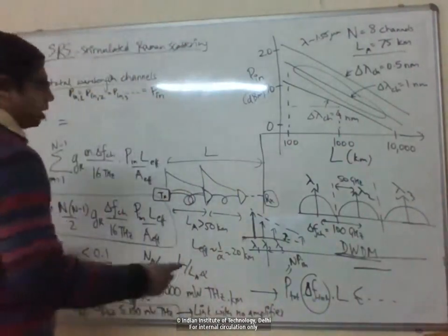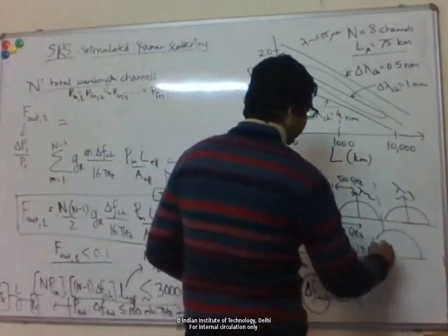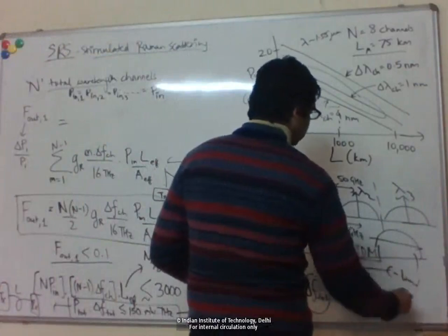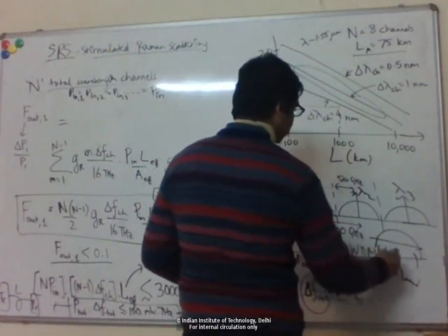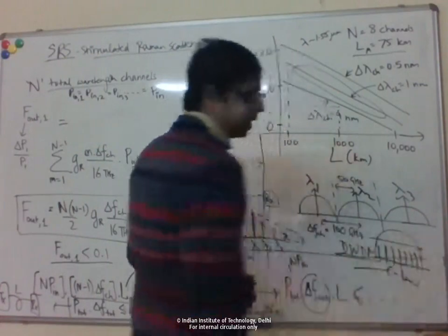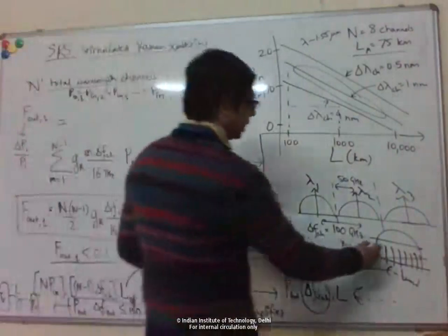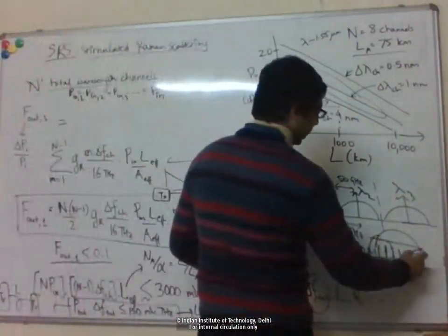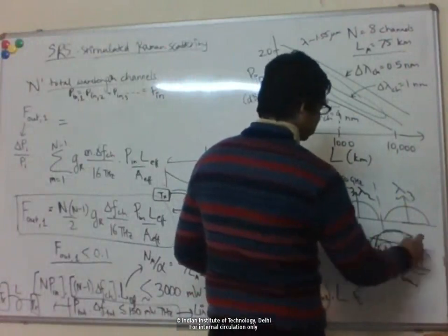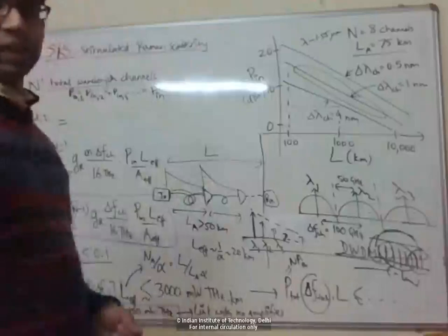But let's say, within the EDFA gain bandwidth, the entire C band can fit. So you can have, for example, 40 channels all within the EDFA gain bandwidth. Maybe at the edges the gain might be different, but mostly for the middle wavelengths, you can get quite flat gain, especially if you operate the EDF in the saturation region.